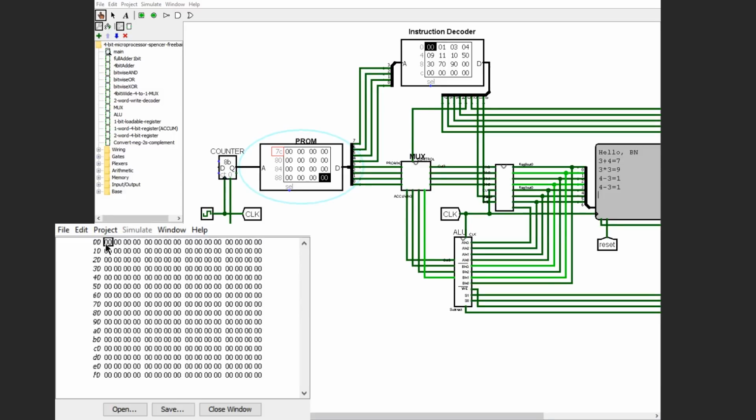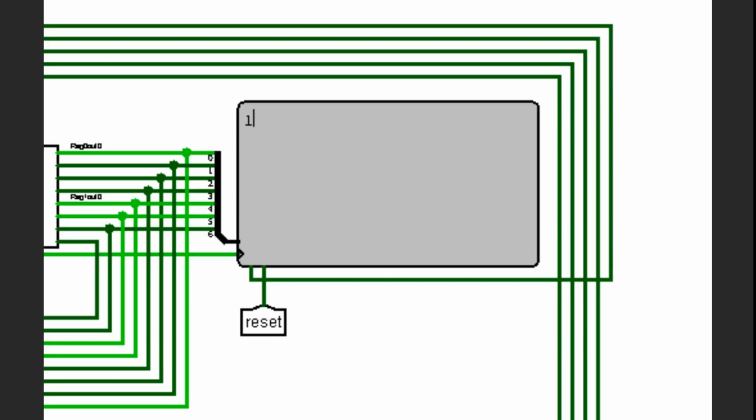So now I'm going to show you the code necessary to perform the hardware subtraction. You load the number that you want to be negative into register 0. So we're going to do that with 3. And then you load the other number into register 1. And then you perform the hardware subtraction. I added a new opcode to do this. It's A0. And then you save that, and then you load 3 into register 1 for the ASCII code, and then you display it. And we'll run that. And as you can see, we have the result, which is 1.